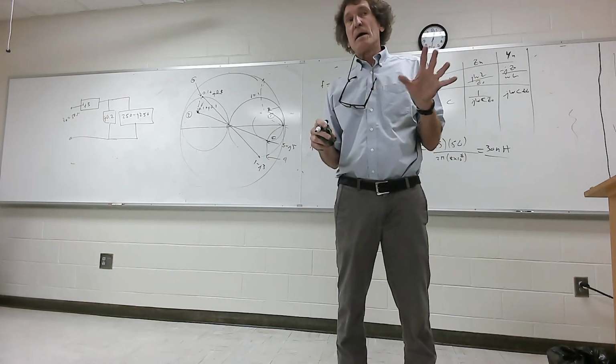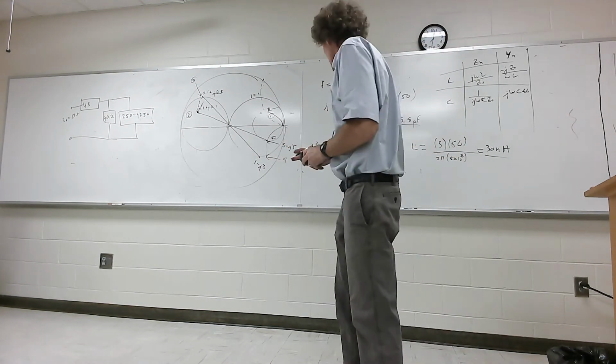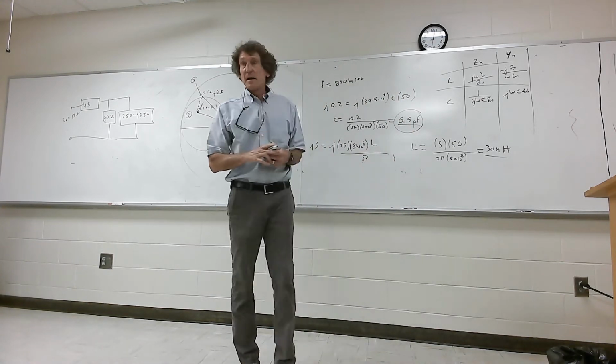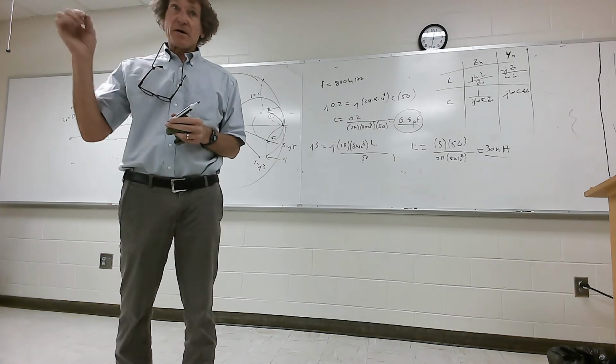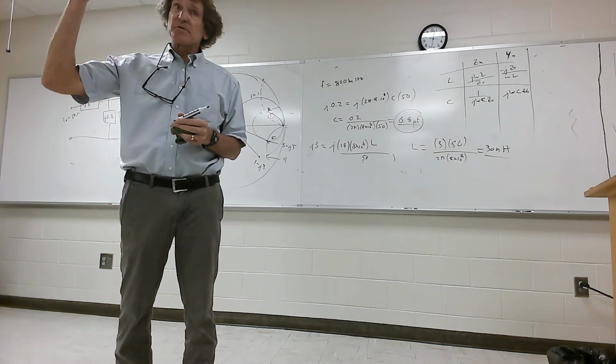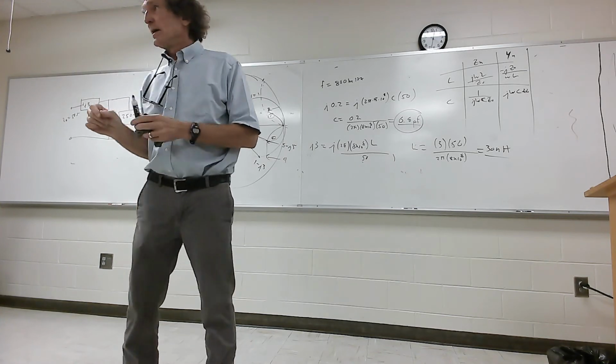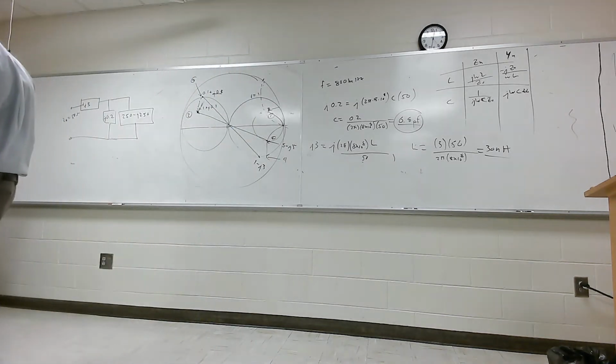All right, now, I want to tell you one thing. This value right here is small. If you're talking about values sub-picofarad, you want a capacitor whose leads you have to trim down way, they have to be super short. If you have a capacitor that says 0.8 picofarads, and they do exist, sometimes I can't believe it, but they do, the leads have to be as short as possible. Two leads that are probably 1.5 inches long, that's almost a picofarad right there. So you have to be careful when you're dealing with that kind of stuff.